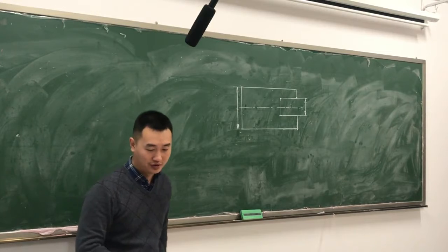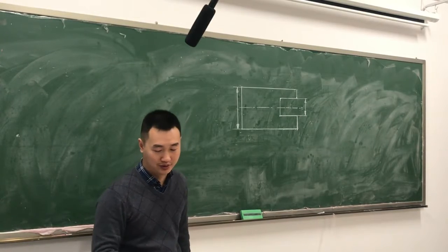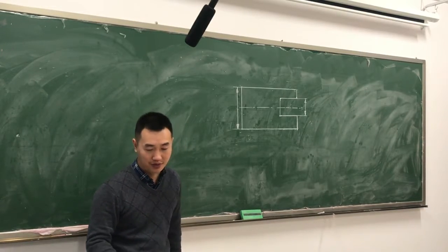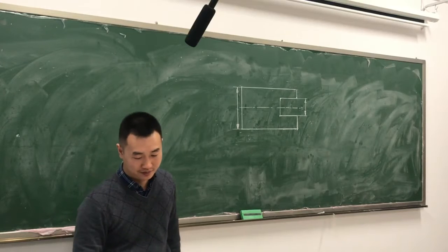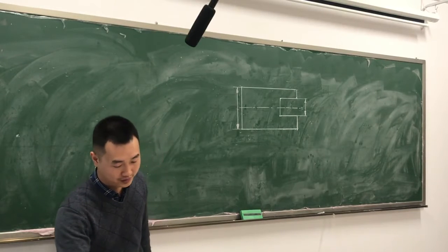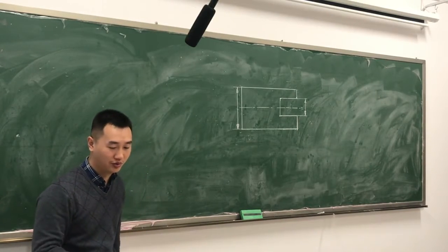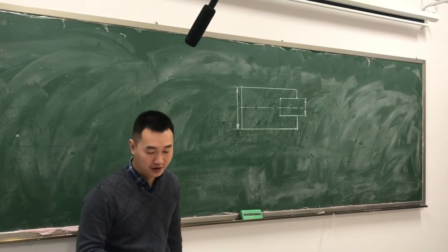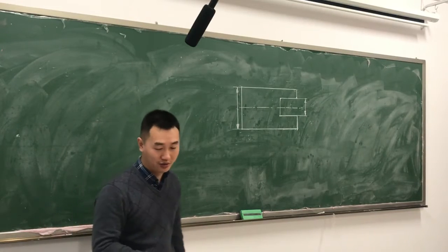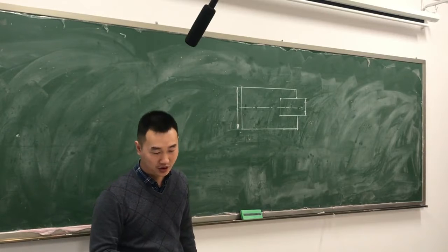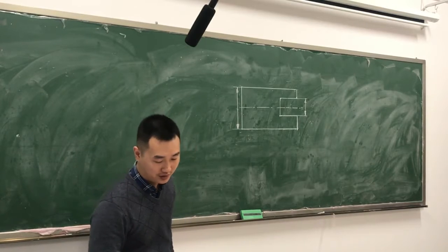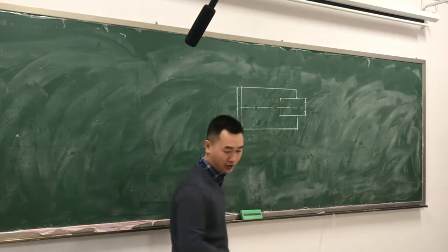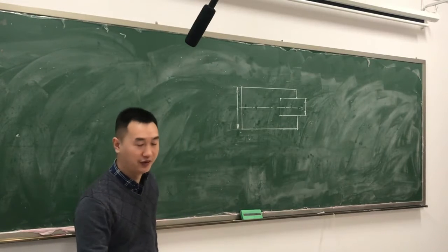All this labeling is for the three geometrical tolerances. The first is the median plane of the workpiece. The flatness tolerance is 0.015. So first we should know where the tolerance feature is, right? The tolerance feature states the median plane of the workpiece.